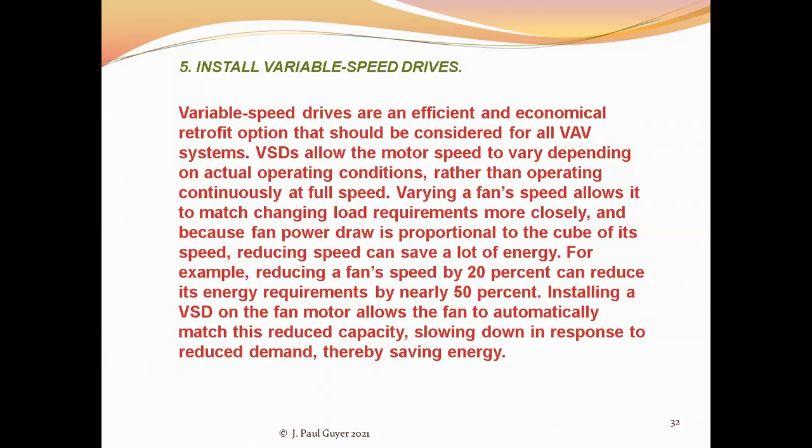So there are good opportunities for energy savings here. As an example, if you can reduce the fan speed by 20%, then the energy requirement is reduced around 50%.